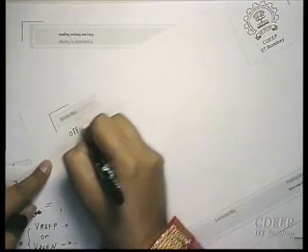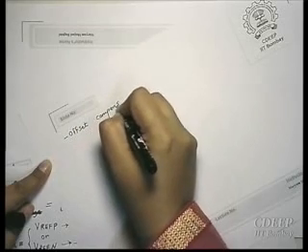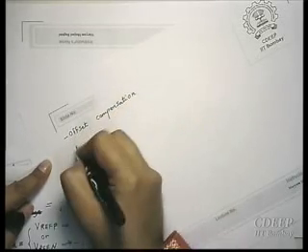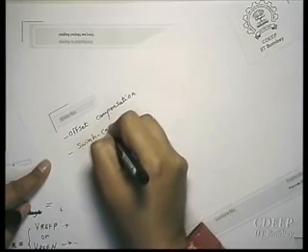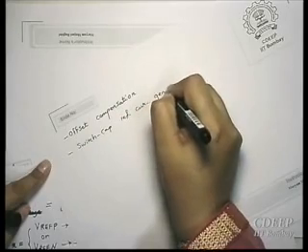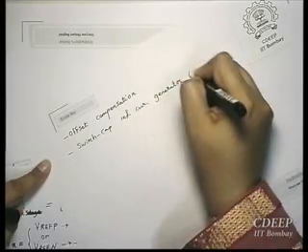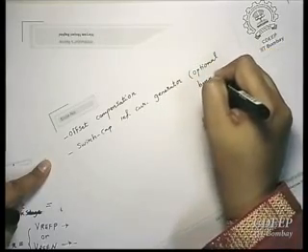So let's make a note for the project. One is offset compensation. Offset compensation of course will be for both cases, SAR ADC as well as pipeline ADC. But the switch cap reference current generator is optional. You will have a bonus if you use it, so do it.